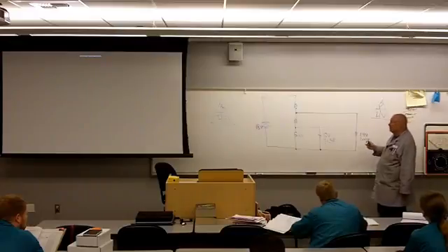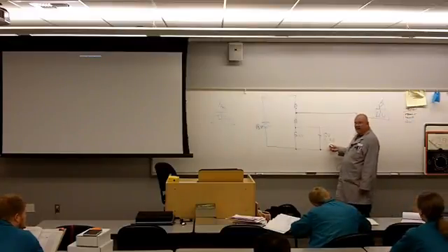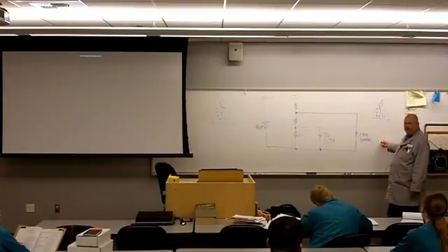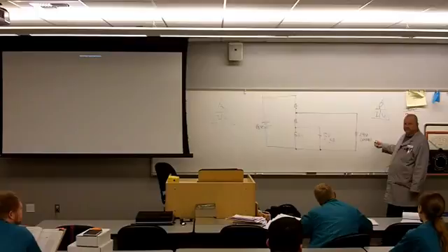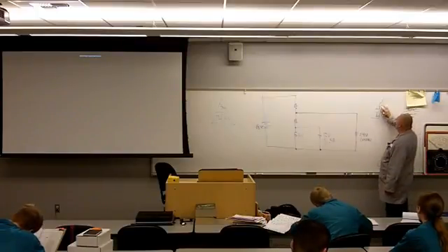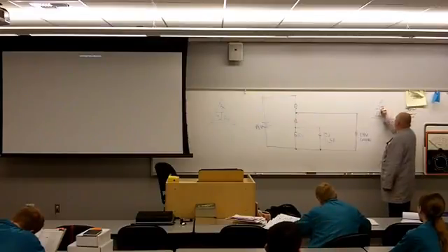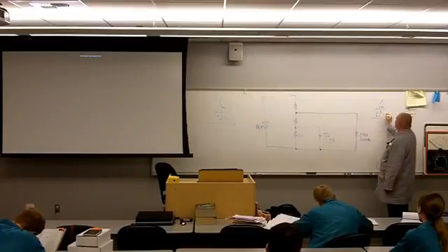That makes sense, right? If a half an amp can power a CB radio, it's going to have to be more than a half an amp to power a 200 watt transmitter, right? Yeah, even at double the voltage. So all I got to do here is power is 200 divided by how much? What's our voltage? 24.